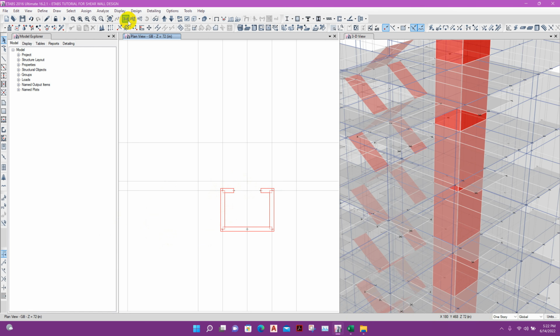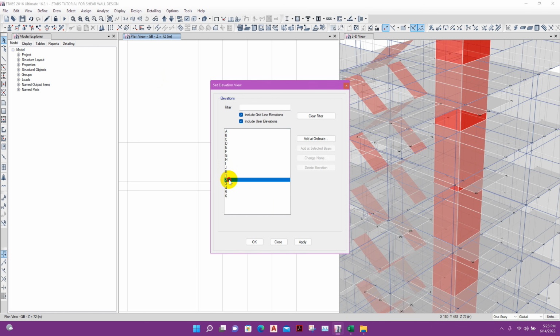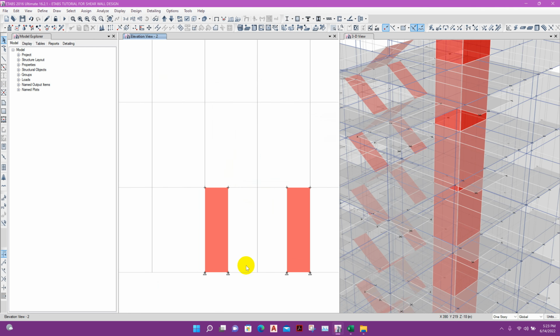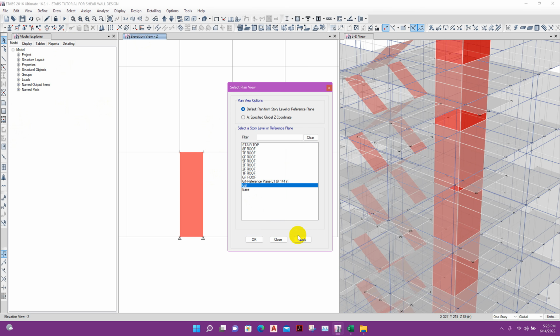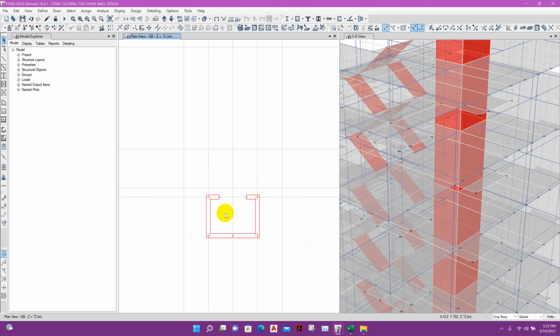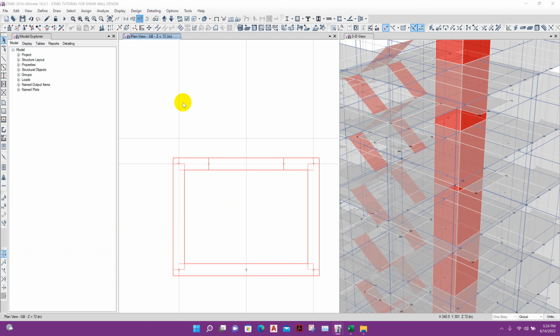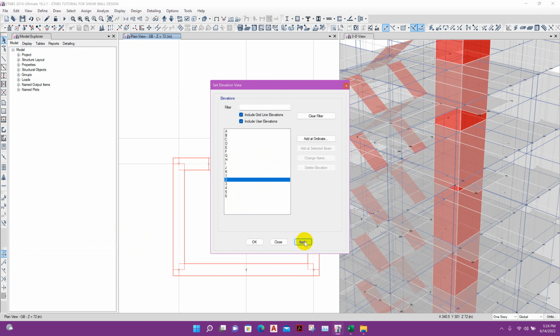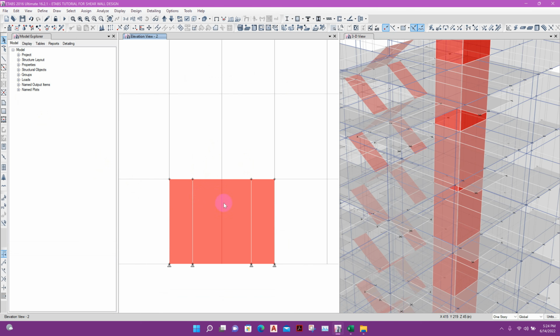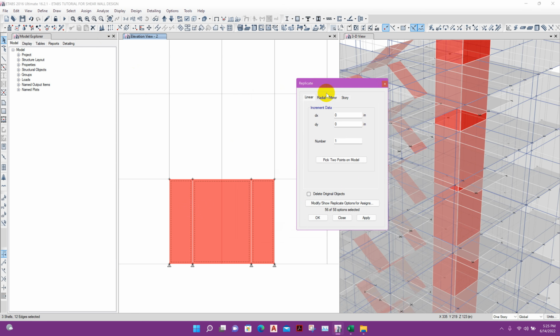like this. Then go to elevation 2. This portion also we will draw wall. Then go to elevation 2, apply. Up to grade beam there will be no door opening. In ground floor there will be opening for lift door. So these 3 we will replicate to next story.